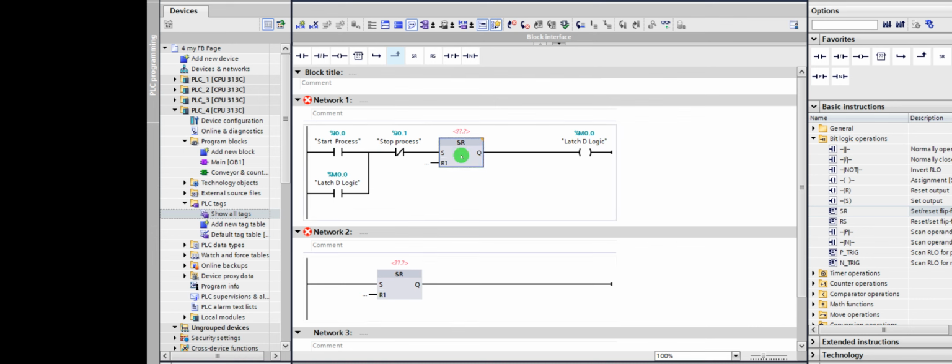So take away this. Let me show you. Now, when I initiate the process from here, this one will get energized and latched here. So in that case, we put this bit on, and this bit will latch here. Beautiful. The same way, I can use this only to generate what I have here. I set this bit on, I get output. If I want to shut it down, I shut it down by energizing reset to knock off my output.